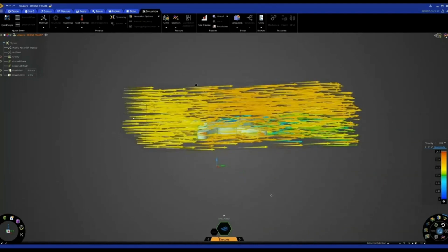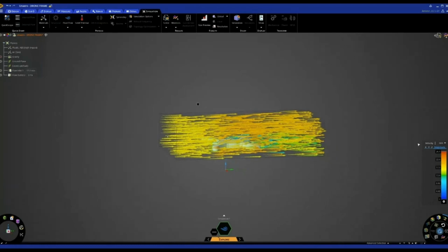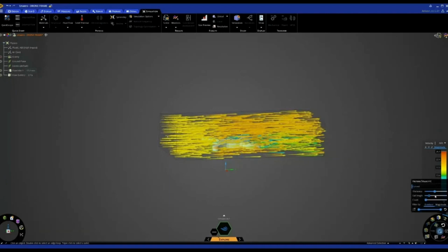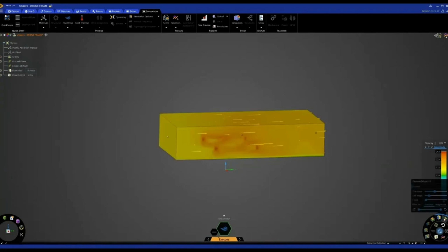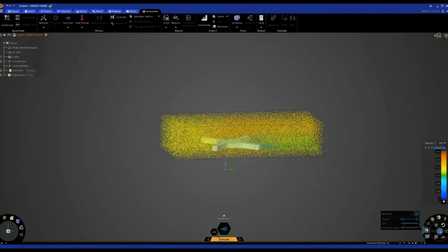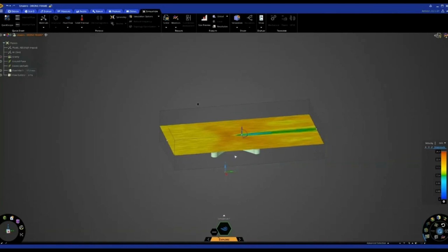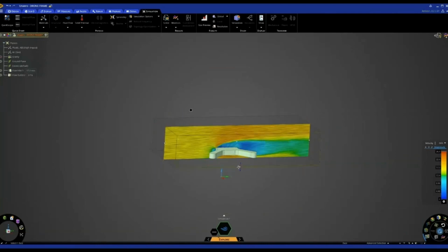So at the moment, we're just looking at velocity, and we are looking at vector velocities. We can show an animation of these, and we can change all our simulation things like thickness, tail length, count, search, just looking for certain magnitudes. We can search for different areas. So that can all be customized to suit. We can change our views to ISO contours, particles, and also direction field. When I'm doing external flow, I like to look at the direction field.